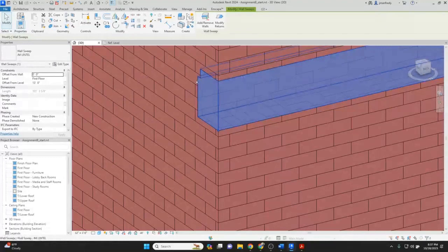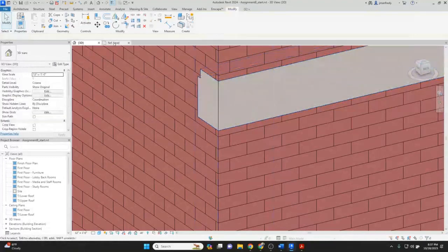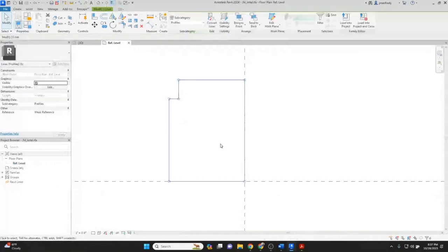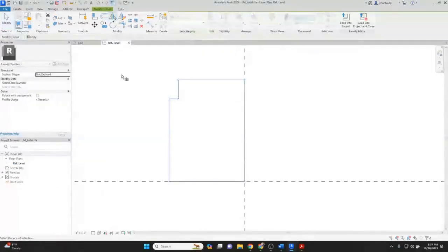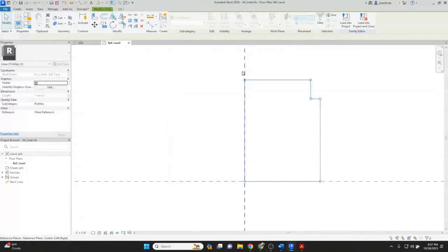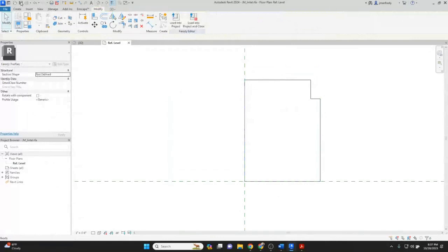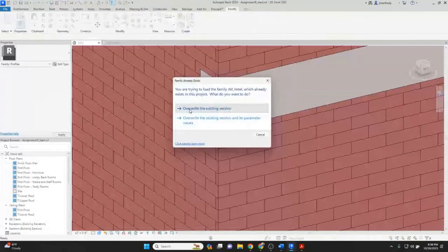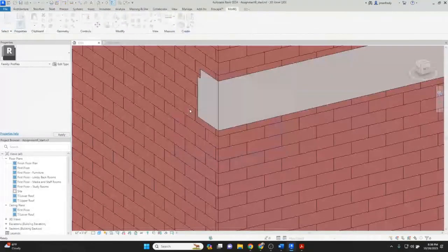And that's a quick fix. You basically come here, take this model and flip it over. Use the mirror command, and don't copy it, make a single copy, and flip it over that line. Make sure these edges here are intact, then save it and load it into the model, and it'll ask for an update. Override the existing version, and it flips it over.